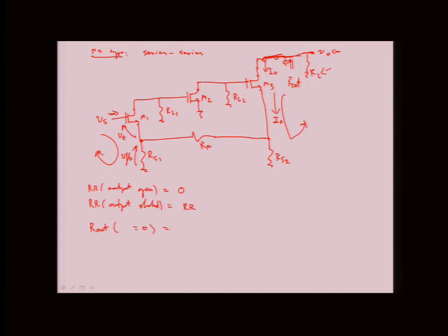So if I don't have a current source here, I still do have RO3, right? So I'll at least have RO3 plus, and then I'm going down, looking into here, what do I have? RS1. Well, you don't have anything looking up M1 because that's also an active path, right? All those I'm nulling down, right?